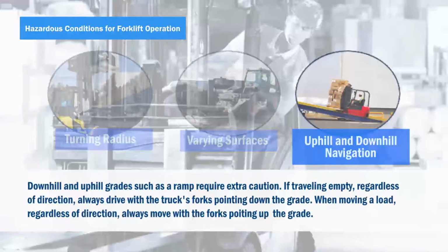Uphill and downhill navigation. Downhill and uphill grades, such as a ramp, require extra caution. If traveling empty, regardless of direction, always drive with the truck's forks pointing down the grade. When moving a load, regardless of direction, always move with the forks pointing up the grade.